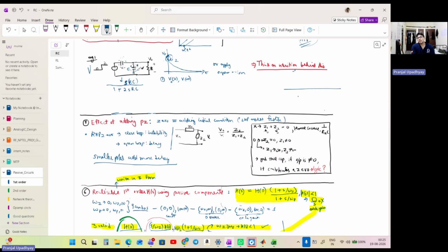And we can understand that every cap contributes a pole. For example, there we have three caps, so we'll have pole 1, pole 2, pole 3. So when a cap got shorted, that means we are at its pole frequency. Now at the pole frequency, since that pole is triggered and mathematically that will blow up to infinity, if this guy is infinite and this is something, my output must be zero. That's why we're checking whether the output is zero or not.